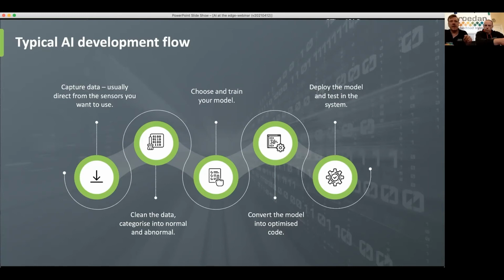The tricky bit. Okay, once you've got that, then you can convert the model into code. Different tools do this different ways. With TensorFlow, you've got a Jupyter Workbench doing it in Python with some cloud access, I think. The STM Cube AI stuff is all online, so you upload your cleansed data up onto a cloud, and it generates, I think, a header file from that. So it's an iterative process, and basically in the end you either get a header file or a C file, which you can then link with your application library to perform the neural net that you're after.